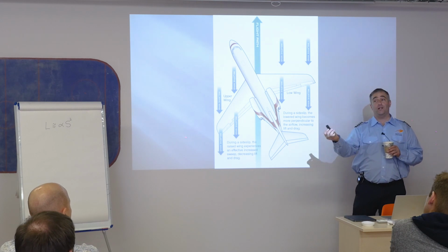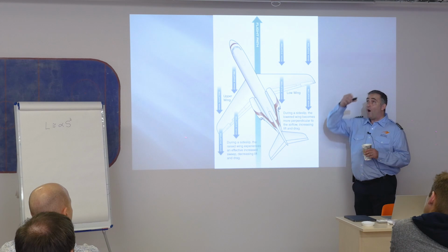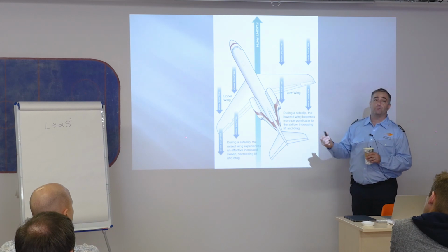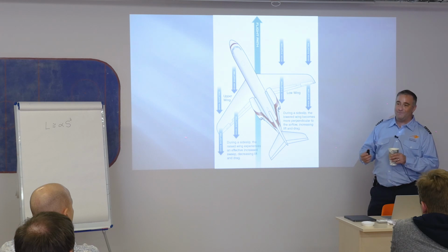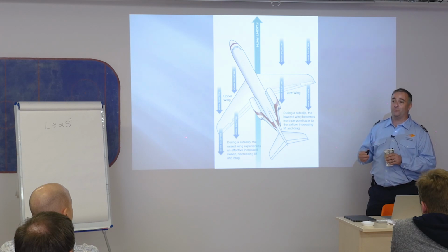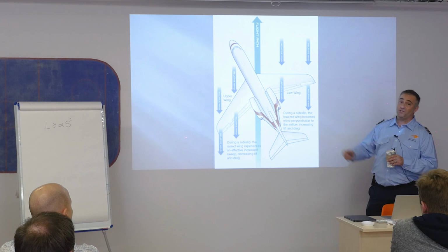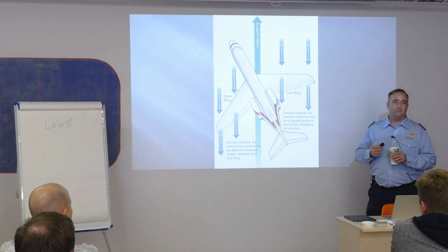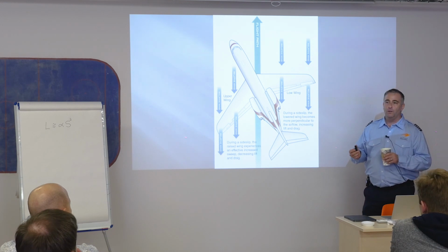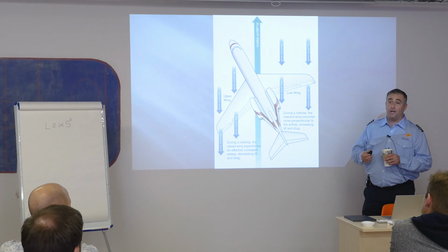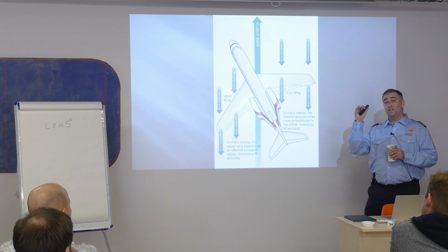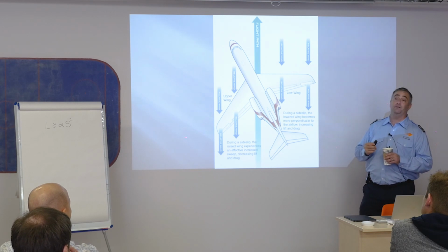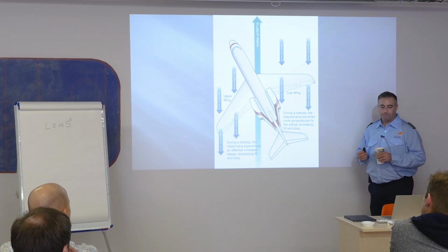In fact, on Air France 447, quite a few very, very smart people agree that the yaw damper was the only thing that prevented them from entering a spin. It didn't matter. I mean, everybody died anyways. I know it's horrible, but they didn't spin the airplane because of the yaw damper. So the electronics on the airplane were actually trying to work and were effective in helping that airplane somewhat.